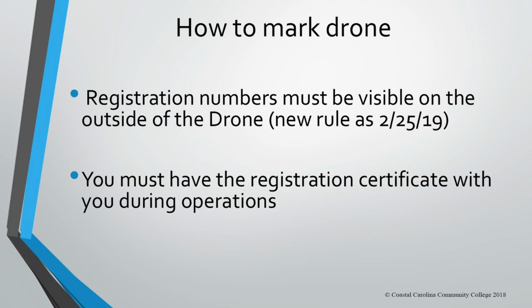The registration must be visible on the outside of the drone. You must have the registration certificate with you during operations. For me, I have hard cases for all my drones. If you lift up the foam padding, I put all my documentation and my logbook under that, so I always have the required information with me when I am operating that drone.